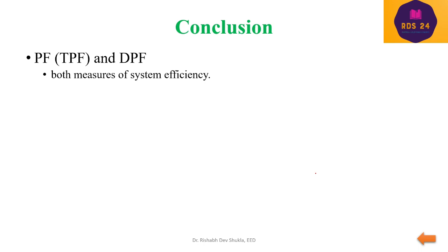Both power factor and DPF measure at the system frequency. These two terms are equivalent in non-harmonic situations. When the system is totally harmonics free, with no distortion, these two factors are equal. Power factor, or total power factor, and DPF are equal. In general, power factor is also called TPF, true power factor or total power factor.